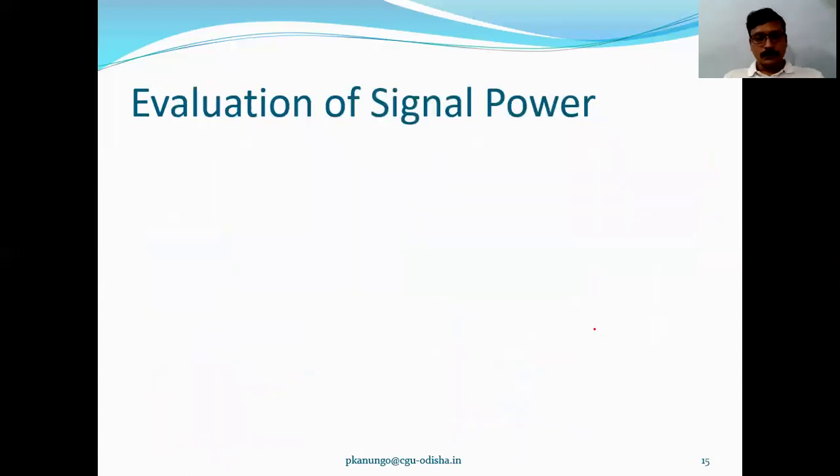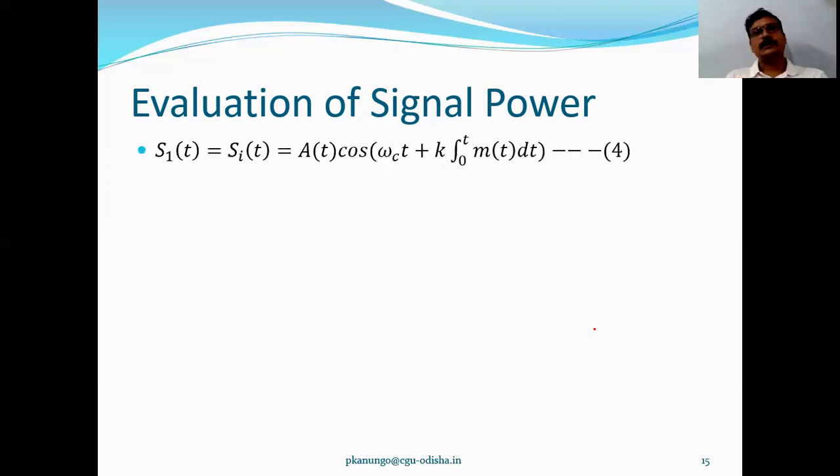But when we go for the evaluation of the signal power, first we will calculate the signal power at each and every stage, stage by stage. Then finally we will get the output power at the output of the baseband filter. Similarly, we also know the power spectral density of the input noise. Then we have to calculate the power spectral density at the IF filter, then the differentiator, then the baseband filter, or low pass filter. So first we will go for the signal power calculation.